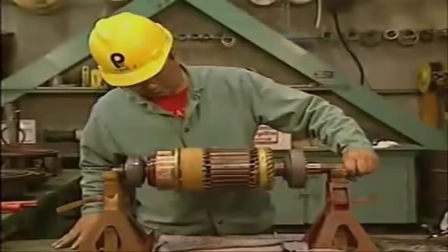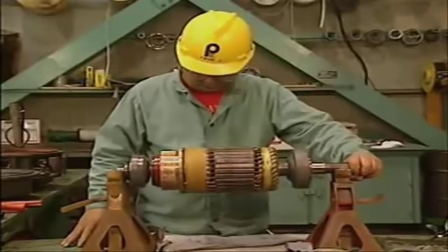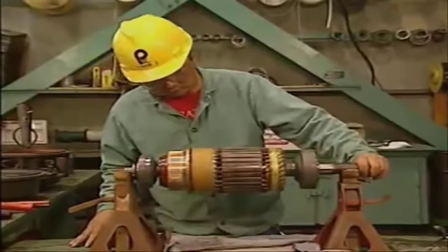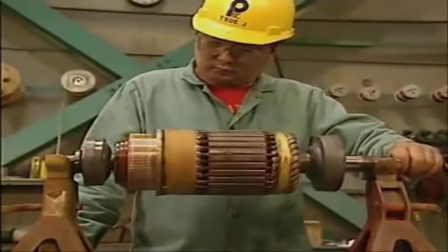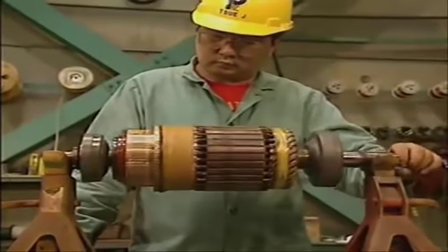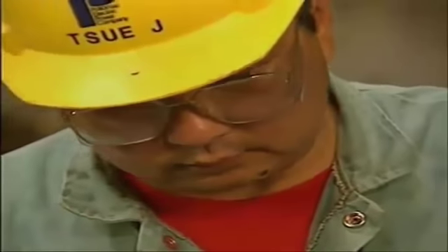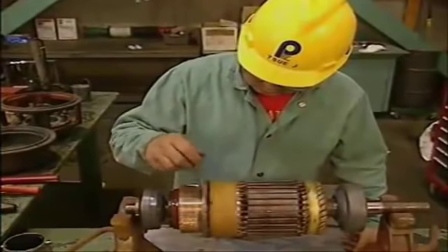ground. Next, the armature winding should be checked to make sure that there is no evidence of solder being thrown out of the risers. The presence of solder is usually an indication that the commutator has been overheating, either because of a motor overload or because there is armature winding damage. The area behind the risers should be checked to make sure that there is no melted solder, dirt, or carbon dust there. If any foreign particles are found, they should be removed with an approved cleaning solvent, rags, and a